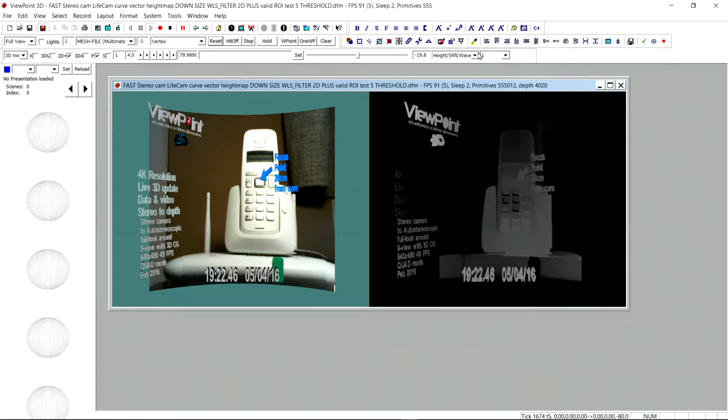So let's look at the slider here, the drop down slider. We've got disparity. When we put the cursor over the slider, we'll see it says adjust 3D disparity, 3D stereo shift, displacement, stereo displacement, lambda and sigma using shift control alt. So we're going to set the range to 1, and then we're going to adjust the sigma. You have to make sure you've selected the correct object. You can see now we're blending the 3D depth map settings, removing some of the noise.